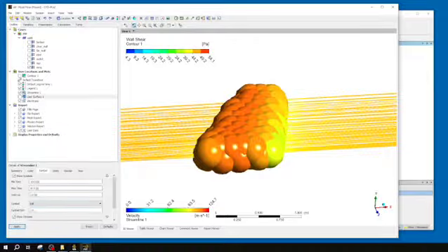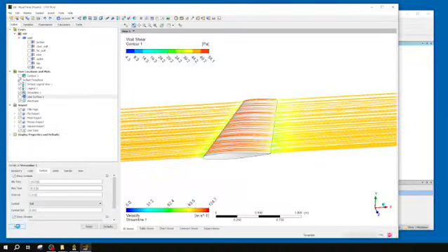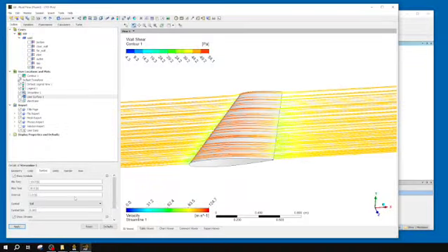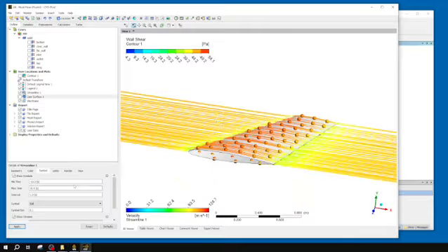And if I decrease the symbol size to 0.001, apply that, maybe just 0.1, my bad, or 0.01. Let's see, just 0.1, my bad. Yeah, there you go. You can kind of see them all starting in their kind of places. You have a max and min time. Let's set the interval to like 2.